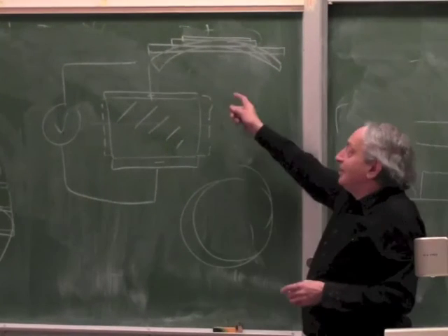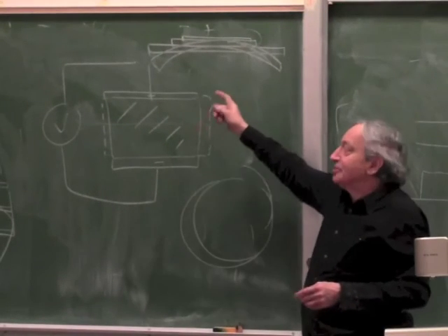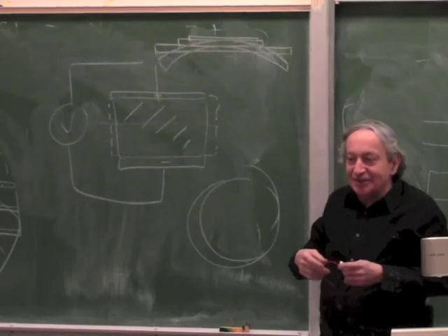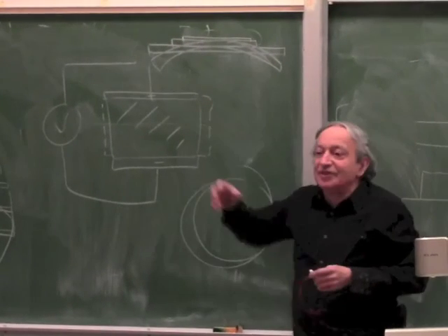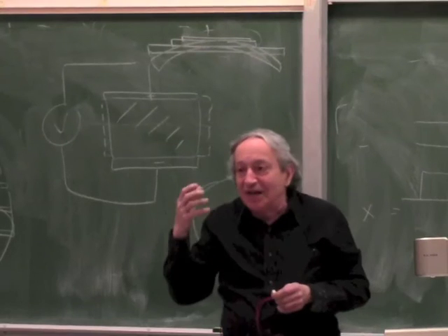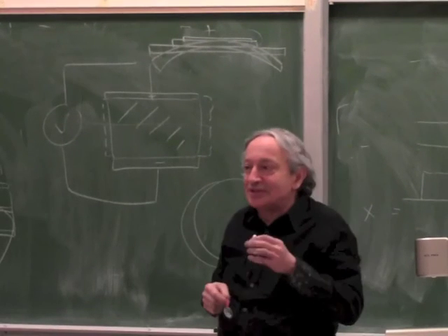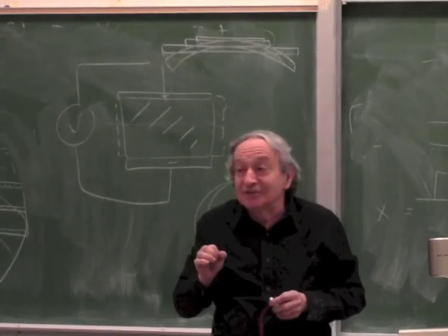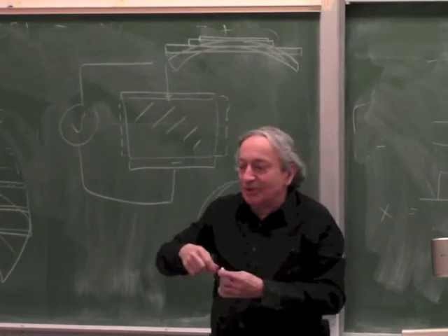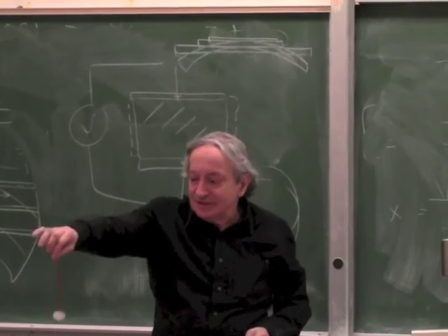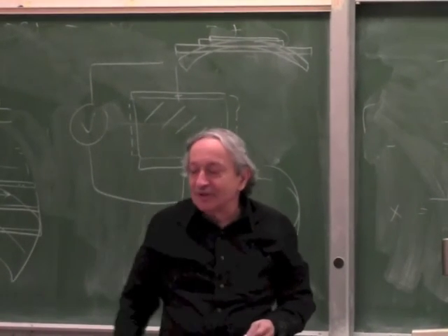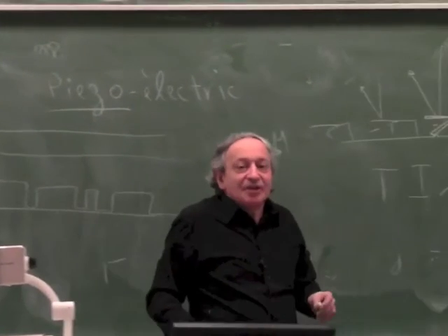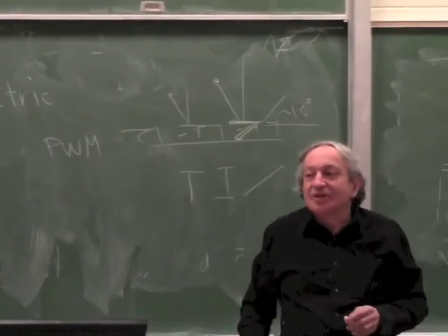Typically, it's driven by a few kilohertz, because you're trying to drive it at its mechanical resonance, and because these things are stiff, their mechanical resonance is high, so they always make this annoying sound, especially because they're small. If they're small, their mechanical resonance is high. So pass it very quickly because the lesson is coming to an end. Just have a look at it. You can identify the 2 electrodes in the piezo. Just pass it quickly. So these are piezo actuators.